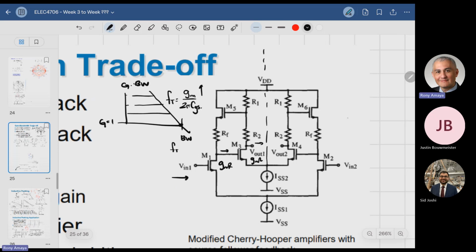Really cool thing they've done. This is actually called an FT doubler if the devices are the same. So we can all clearly see that we have improved the transconductance. But the problem with a standard device is that if I increase the size, I also increase its periphery, I also increase its input capacitance.